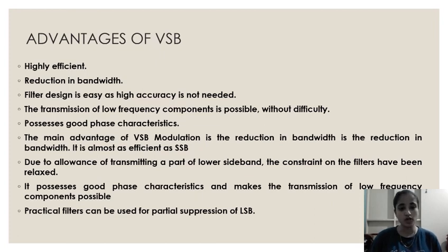It is almost as efficient as SSB. Due to allowance of transmitting a part of the lower sideband, the constraint on the filters has been relaxed. It possesses good phase characteristics and makes the transmission of the low frequency component possible. Practical filters can be used for the partial suppression of the LSB.